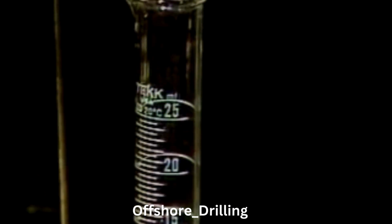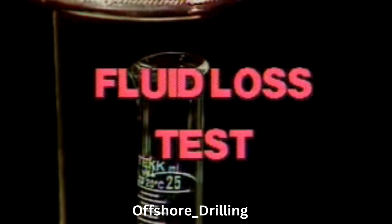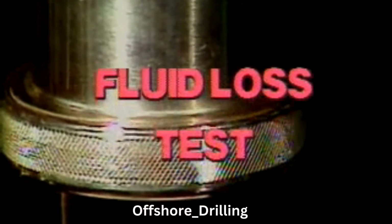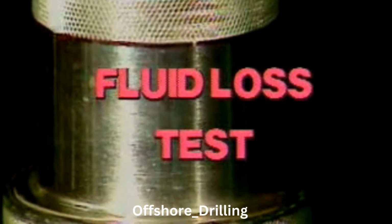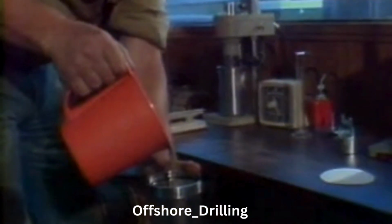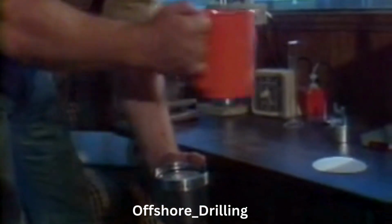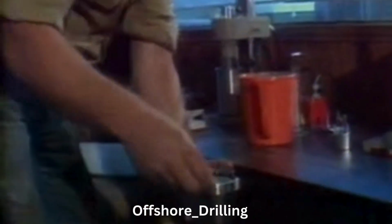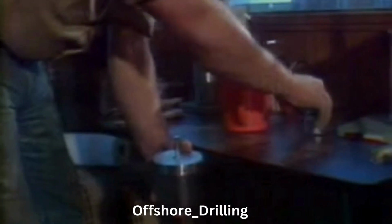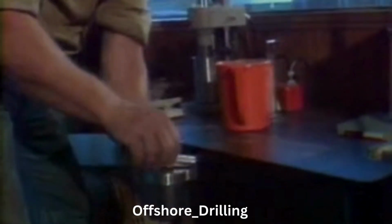The next test he'll probably do is called the fluid loss test. It's a test that'll give him an idea as to how much fluid is lost before a permeable formation is sealed and how much of a filter cake builds up. The idea is that a sample of mud is put in a pressurized container that has a 9-centimeter filter in it. Under a pressure of 100 pounds per square inch, the mud is strained for 30 minutes.